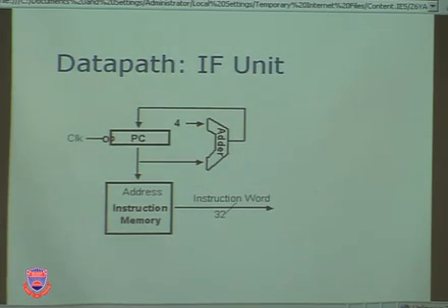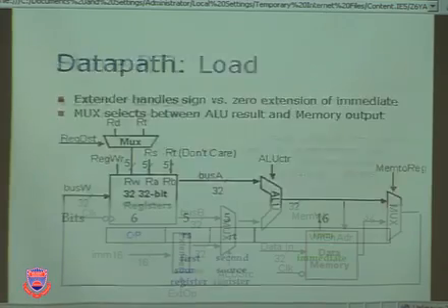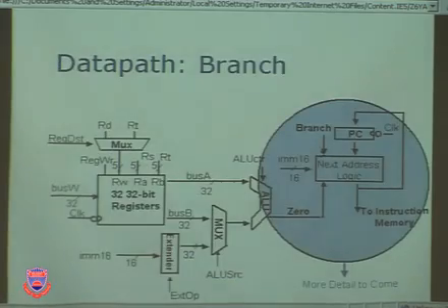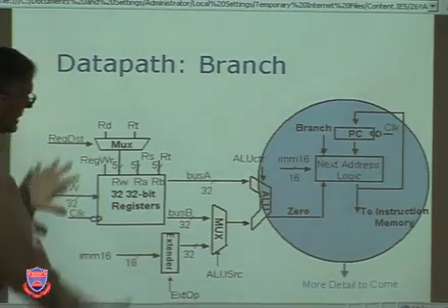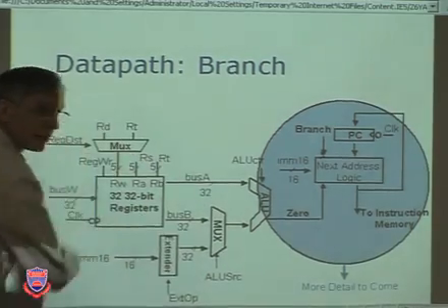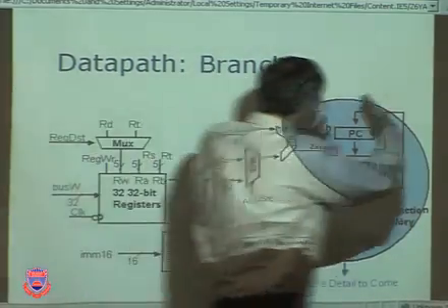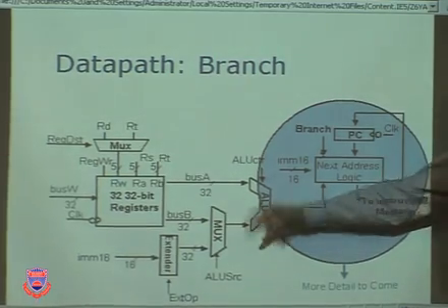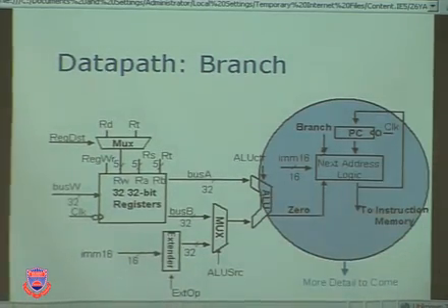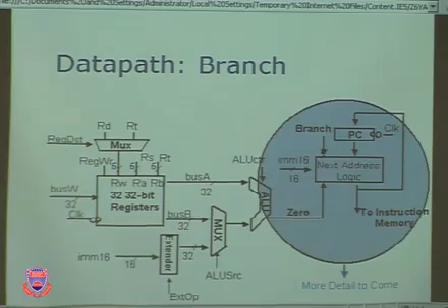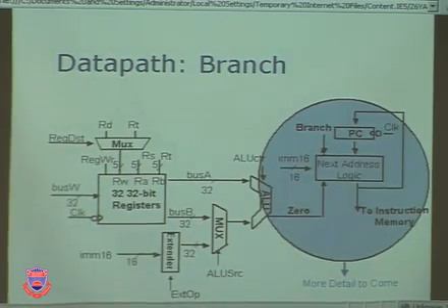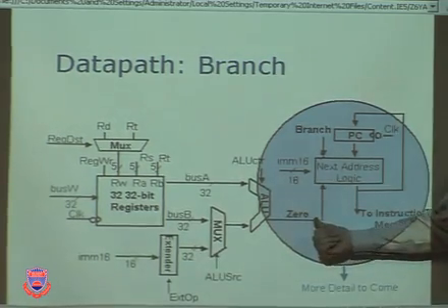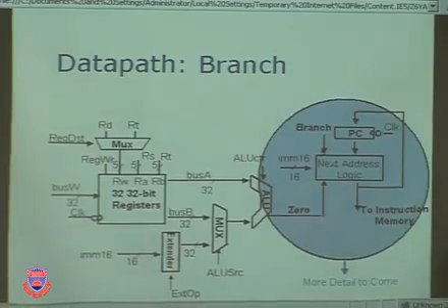All right, then you remember that we then said, okay, great. So branching needs to be able to do something interesting. So we need to look at the following. Not this. This is the data path computation part. This is the next instruction stuff. And look what we're doing. The ALU, after it subtracts two things, says, are we going to take the branch, yes or no? And the 0 signal is the yes or no, if we're going to take it.